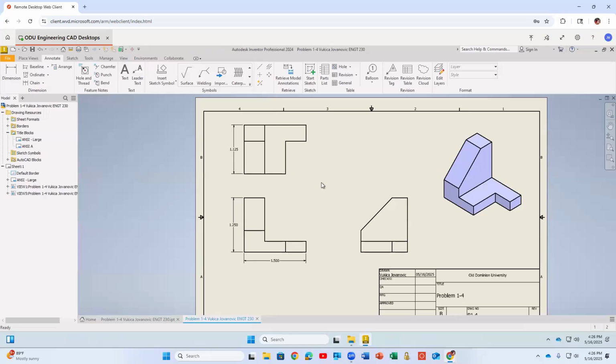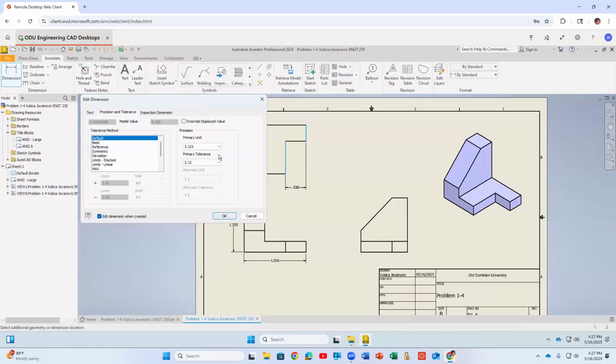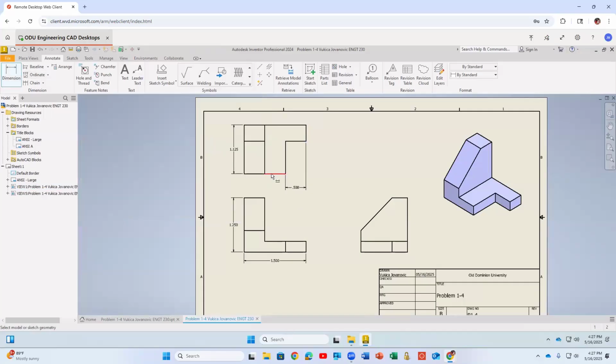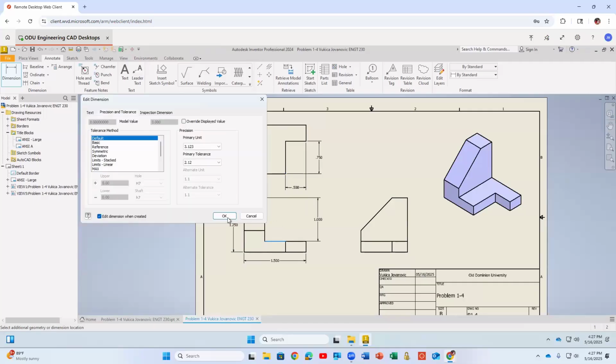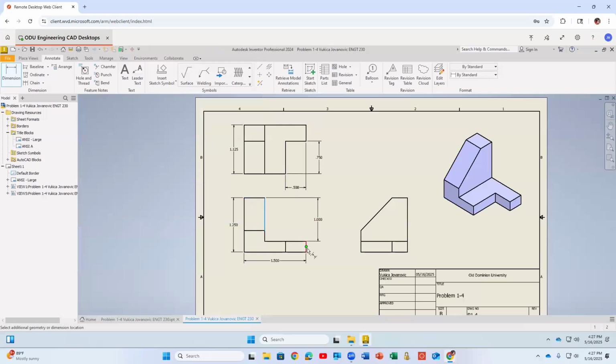So now I have to add where the gaps are. What did I remove? You see, we remove something here. So if you want to talk to your machinist, you can say, hey, you've got to remove this size. So if I'm dimensioning for a machinist, I can say based on what I'm removing. Look, I'm dimensioning that, so I'm giving information, removing that from that side. I can do the similar side here. Say, hey, can you remove that? So that's one approach to dimensioning, just saying what you need removed.